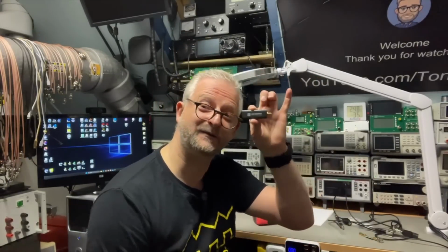Also very well done on the software. It does create a virtual port when you try to adjust the settings, but you don't need to worry about it. It just detects the device automatically. You are able to adjust a little bit the amplitude, which is great because maybe your 50 ohm pass-through dummy is just a little bit different than the one they used. And also the frequency, of course, you can do from a few K all the way up to 300 megahertz, which is great.